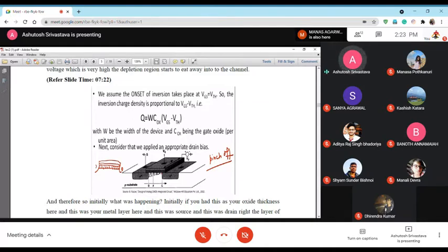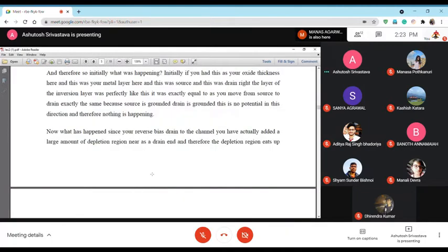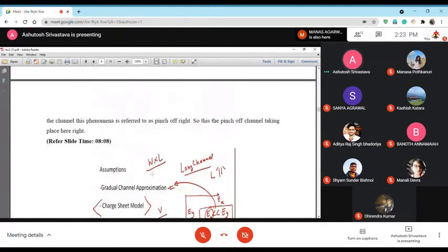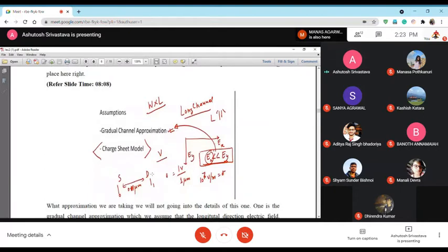The important thing here is that this is being squeezed down over a period of time in a three-dimensional manner. Since it is being squeezed down, you are able to miniaturize the transistor size, and you have come to a stage from 10 micron, which means 10 micrometer channel length or gate length. Some industries call it channel length, others call it gate length.